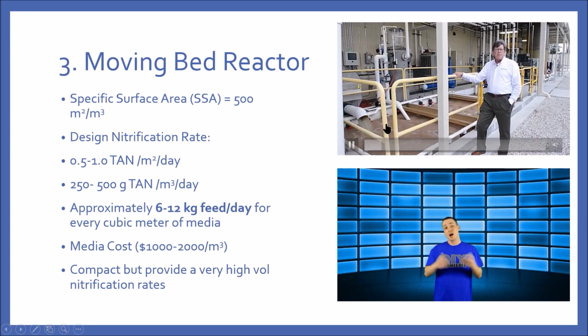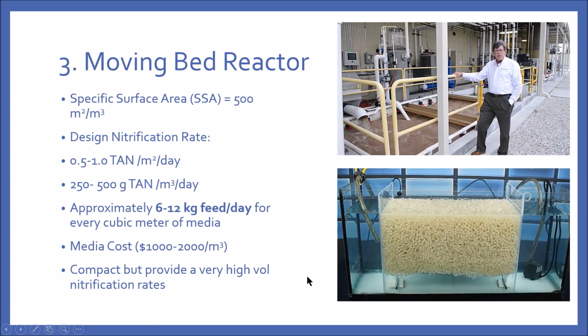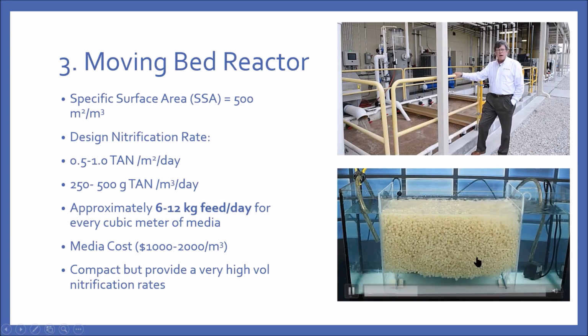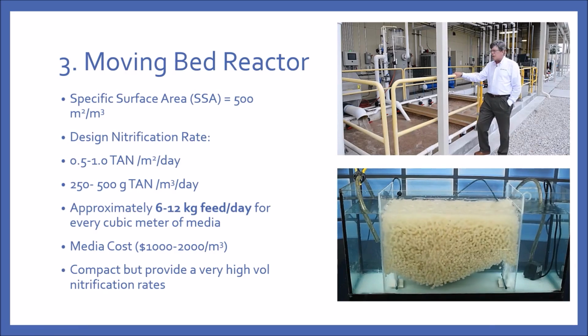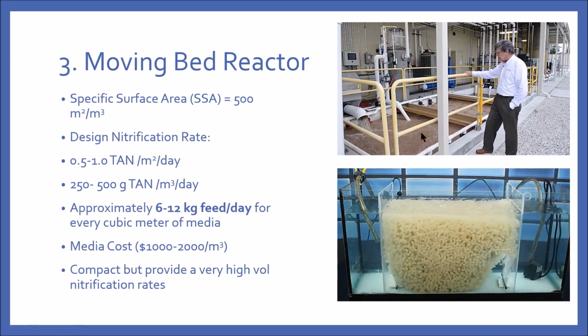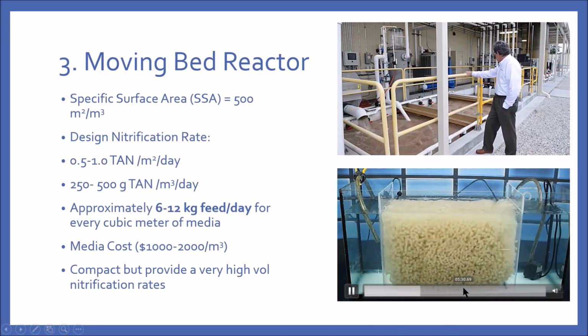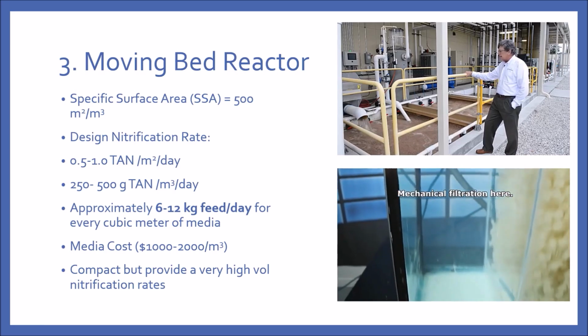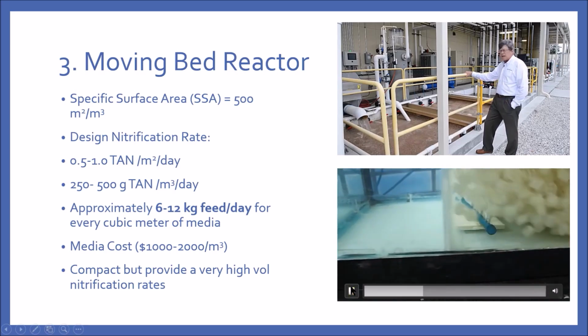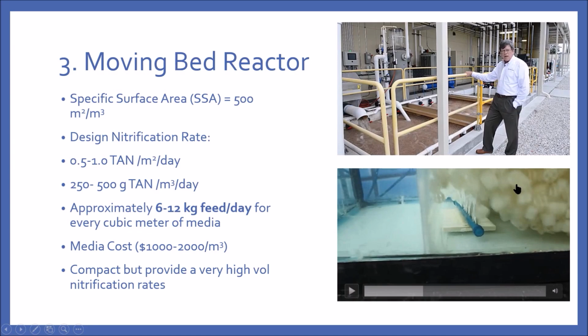So this is a similar plant from the tilapia farm. As you can see, it's just air pumps, and the feed comes from the effluent from the drum filter. It is also commonly used in aquariums for hobbies. And this is how the media is being agitated in a reactor. Similarly, you have bacteria growing onto this media that have the opportunity to not only stay at the bottom, but go up to areas with high oxygen content. As you can see, you only require a small air pump to rotate this moving bed reactor.